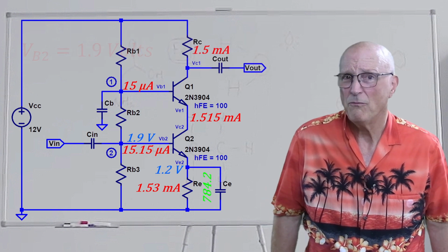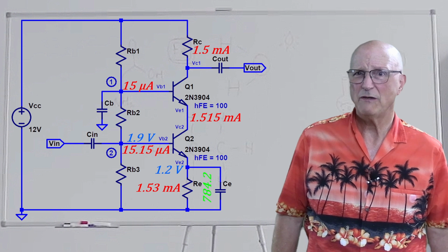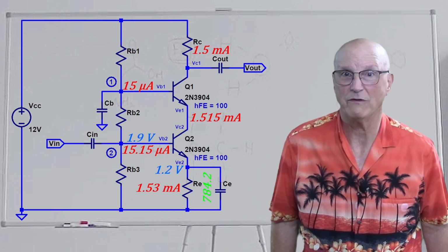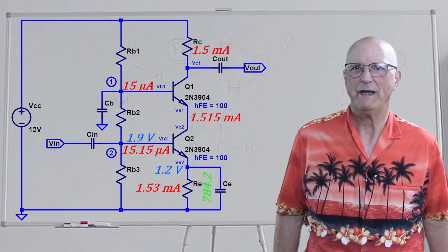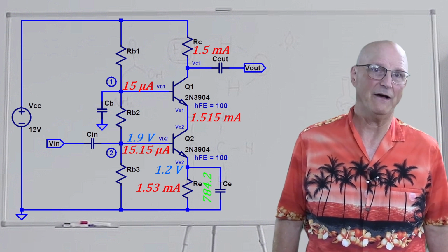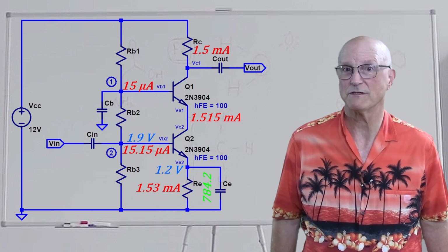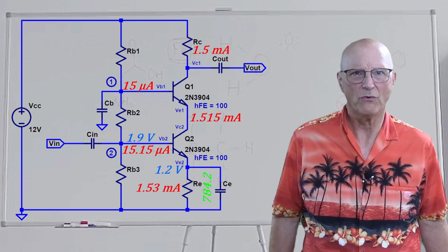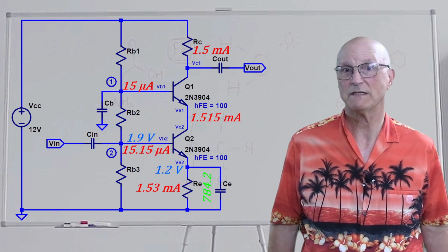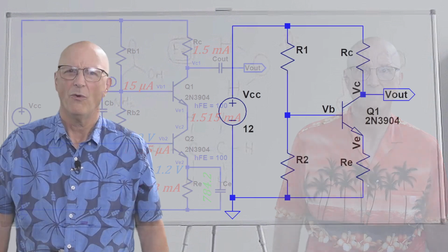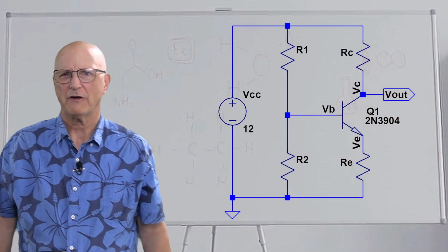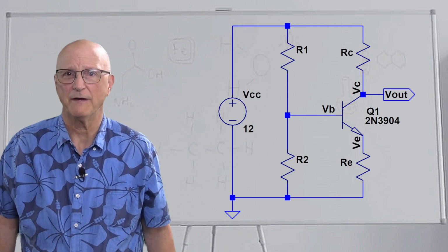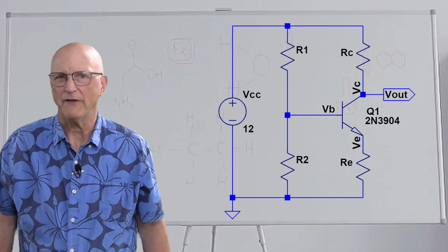Well, to begin with, you might be wondering why I'm going to be doing what I'm doing next with all of the Thevenin equivalent stuff. It is so that we can easily get at the needed values for the base biasing resistors. So, to that end, we're going to pull out yet another rule of thumb from the beta-stabilized common emitter circuit. You remember the Thevenin equivalent circuit for the biasing resistors of the beta-stabilized common emitter circuit. It looks kind of like this.